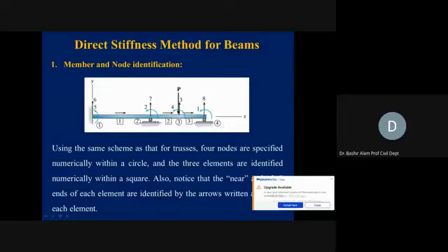Then you can see without circles and without these squares, these numbers, these are showing the kinematic indeterminacy now. How we are going to proceed? We start from the free degrees of freedom, the joints who are free to move. Now this one, if you see, this one is a rotation which is free now, displacement at this joint 4. So we start from the free, this is free, so it is 1.